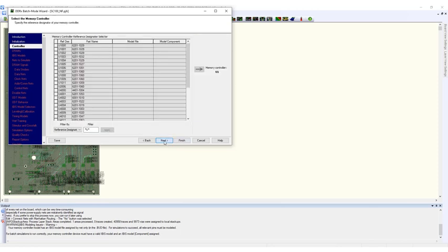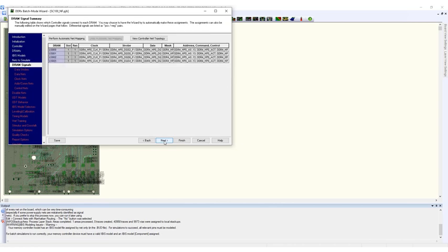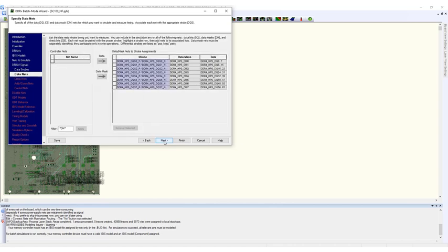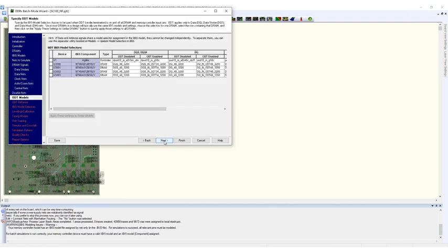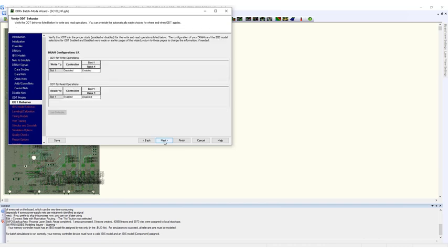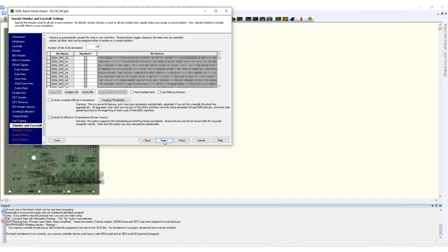The DDR-X wizard helps us to configure a complete DDR4 test bench. All requirements from timing margin to signal integrity characteristics are considered. With the different ODT settings, HyperLynx is capable to simulate the read and write use case. Since this is just a fast first check and time to results matters a lot, we will uncheck the crosstalk and power aware simulation. These checks are done in the final sign-off by Rory.